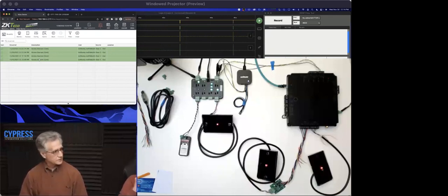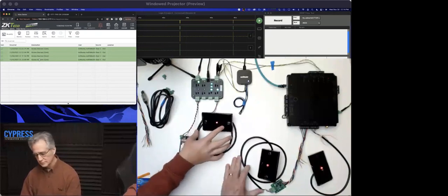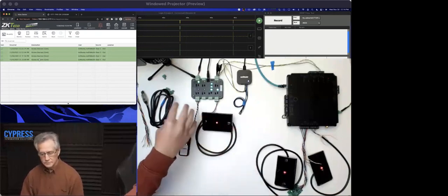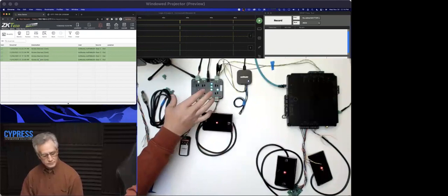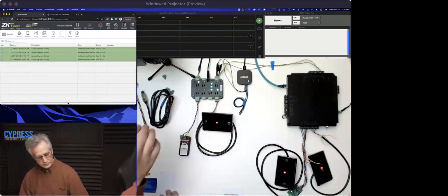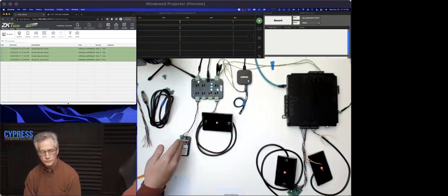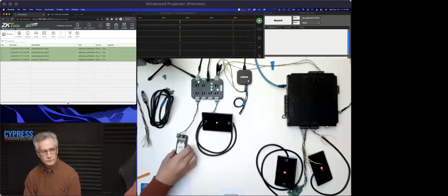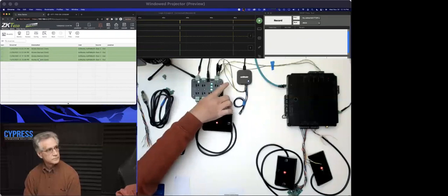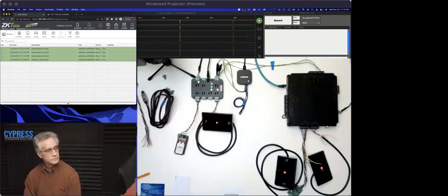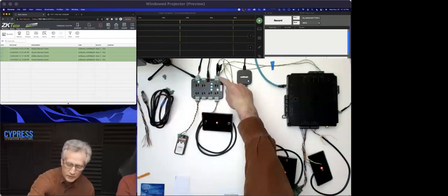So what's next? Yeah, so finally we have our OSDP reader that's connected to our panel through the OSM hub. This is set up so that way if we needed to comm set the reader for some reason, we could do that very easily here. As well as we have our Saleae device connected so that way we can actually see what's happening. Yep. So we just have some clips that are clipped right onto the RS-485 lines.